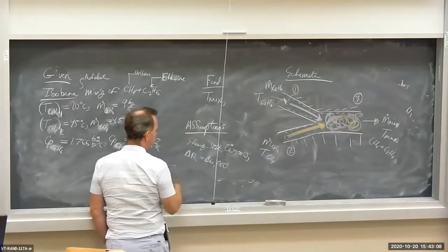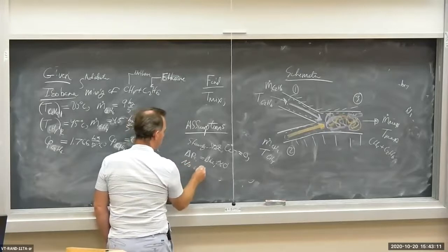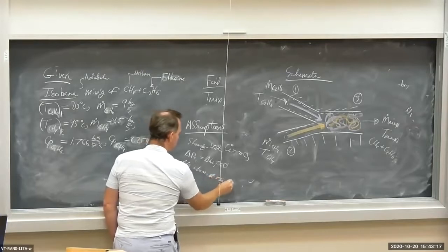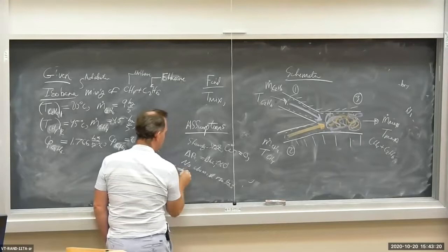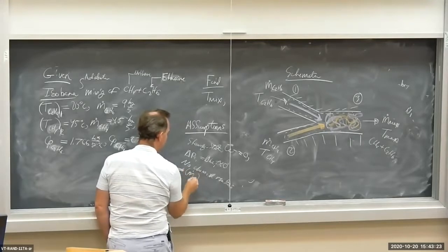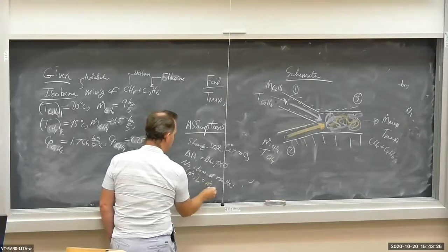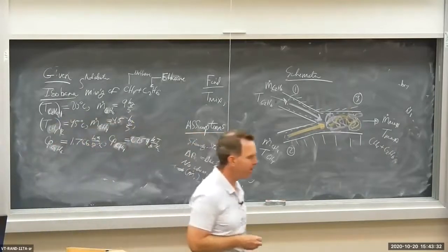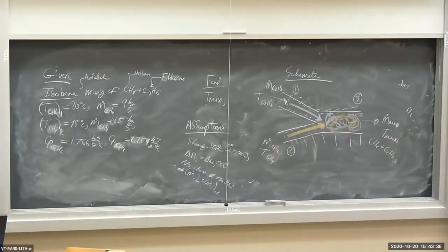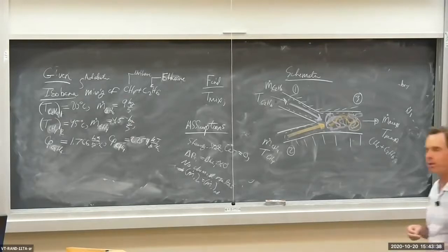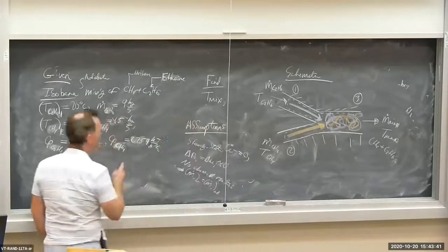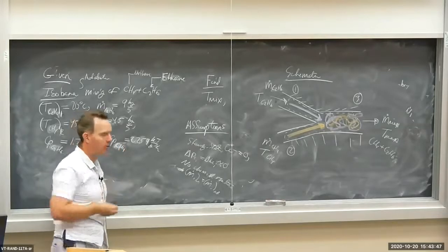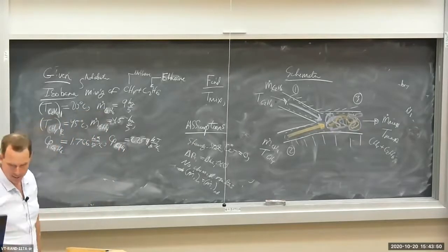So I'm going to write down here as an assumption, no chemical reactions. So what that means is m dot i in equals m dot i out. I'm not burning methane or converting methane into ethane. I'm not producing any, there's nothing chemical going on here, it's just mixing. So the mass flow rates for each component at the inlet and the outlets must be the same, okay? Summed over all inlets versus the outlet must be the same, okay?